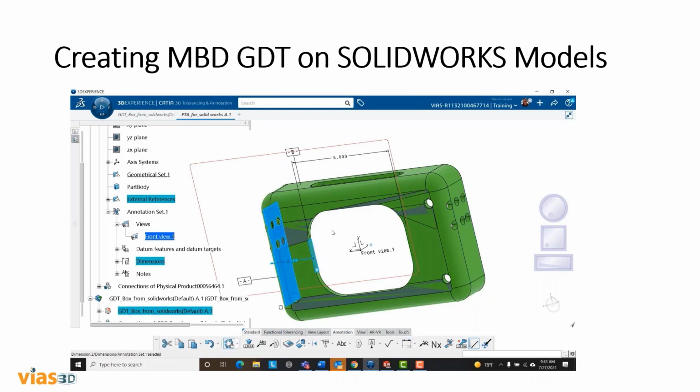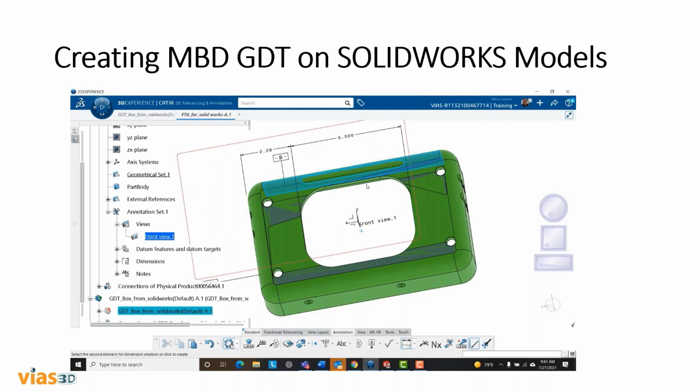Put one more dimension on there. And again, you could use GD&T on this in a way that made a lot of sense. Put some true positioning on your holes, annotate any datum you want to. You'll see later on that I use a surface profile.